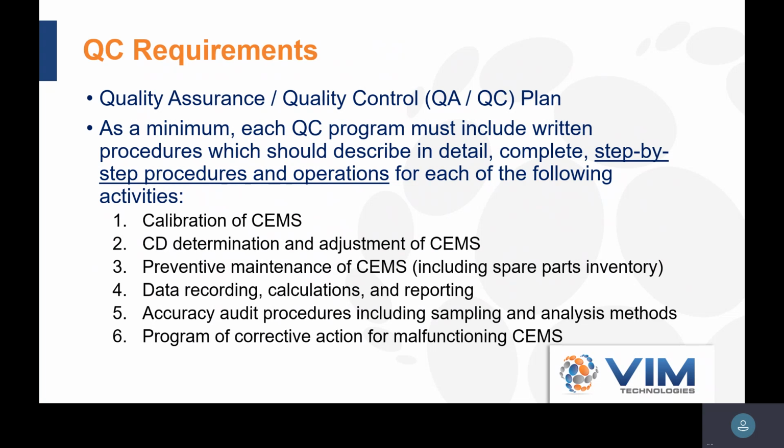If you have any scheduled maintenance activities, maybe every quarter you rebuild a sample pump, change a probe filter, or flush out the sample line, you need to have step-by-step procedures for each of them included in your plan. And also you're required to have a spare parts inventory.